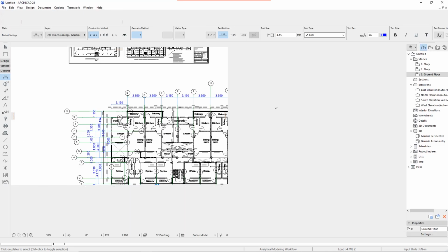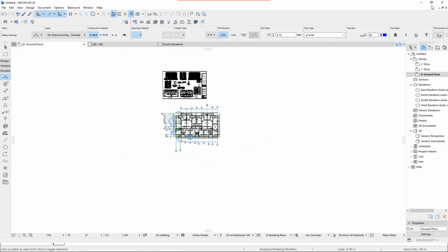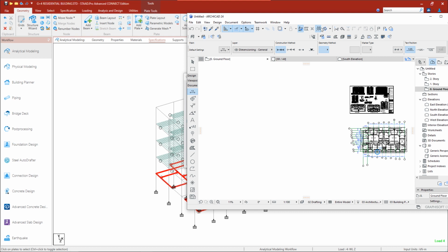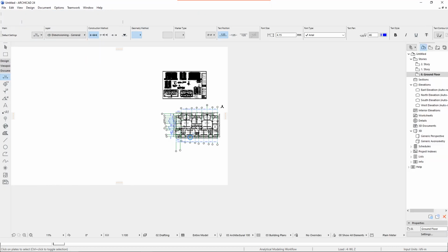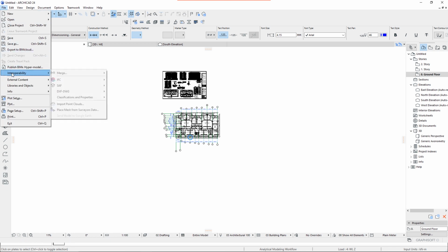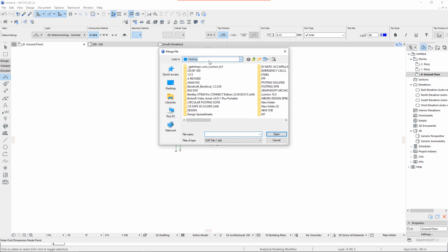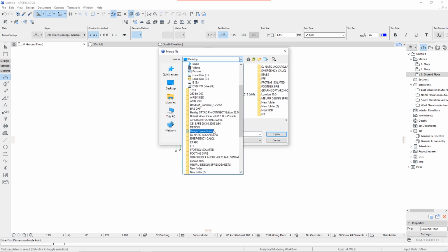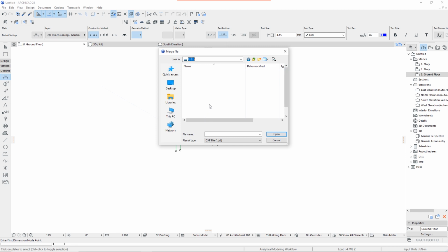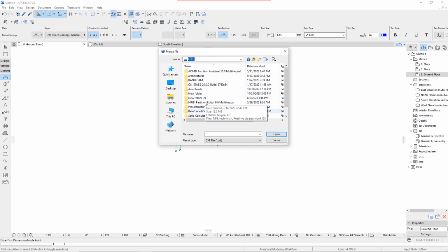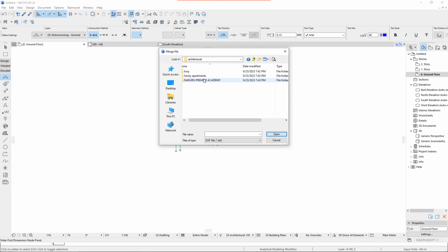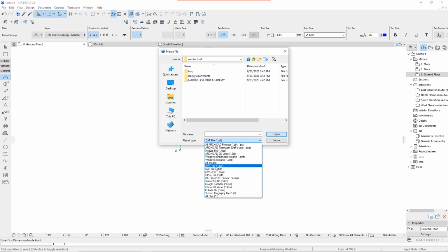Then I will go to commands. Beam design add, column design add, take off add, equals beam design, select beams parallel to X and Z, assign X, columns assign parallel to Y. So it's selected, assign this, and then you can see the 3D rendering.